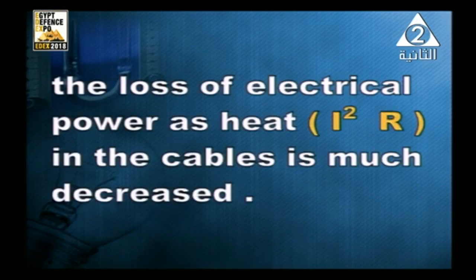Thus, the loss of electric power in the form of heat, which is given by the expression I squared R, is much reduced. Since we decrease the current and the current in the expression is squared, the loss in power in the form of heat will be decreased.